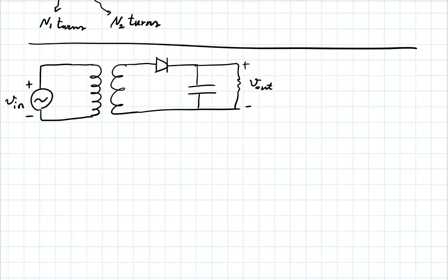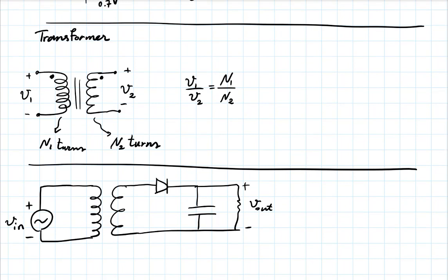But wouldn't the current on the other side, in theory at least, only depend on the load, the resistance, and then basically adding more voltage with the same resistance? Yeah, so it's a very good question. Wouldn't the current on the other side be determined by whatever load is connected? If I have the transformer here, and I put a resistor in parallel here, then the current is dictated by that resistor, right? If that requires a very high current, that means the transformer will not be able to do its job, unless you feed it more current at the input.